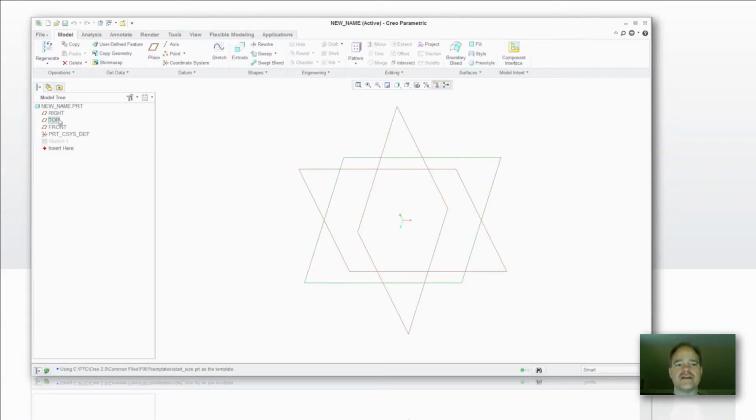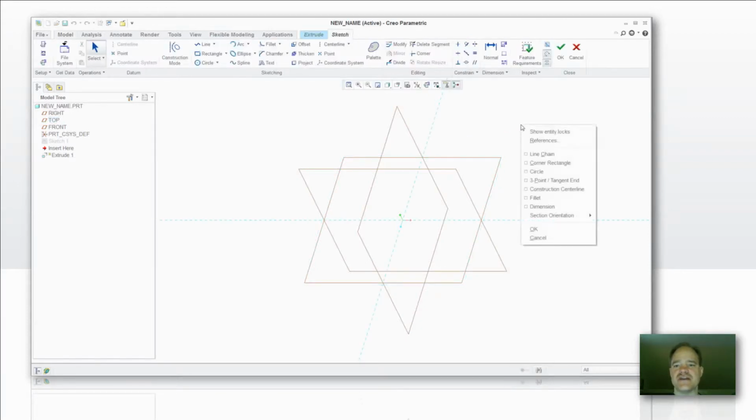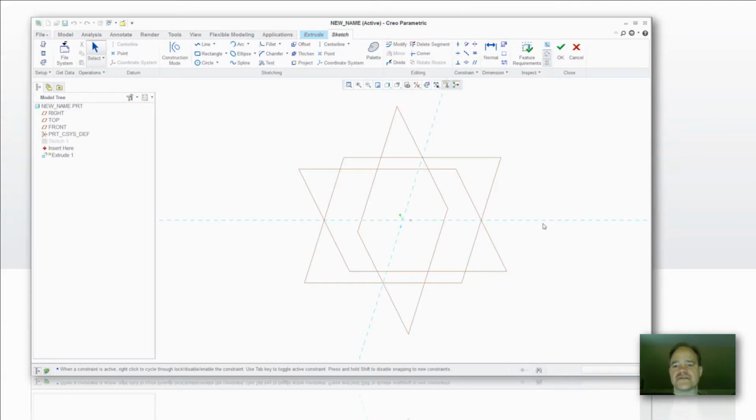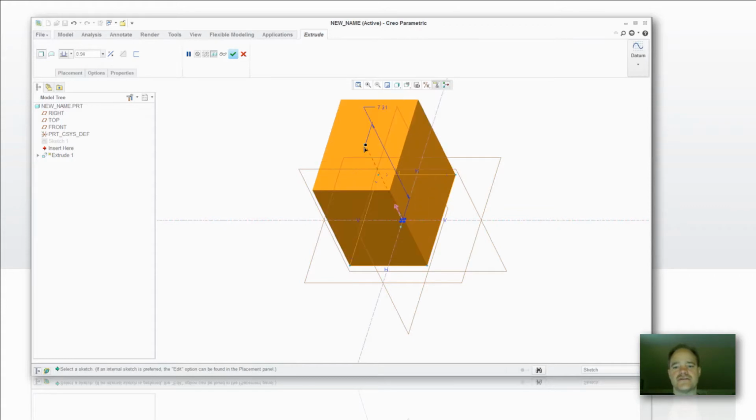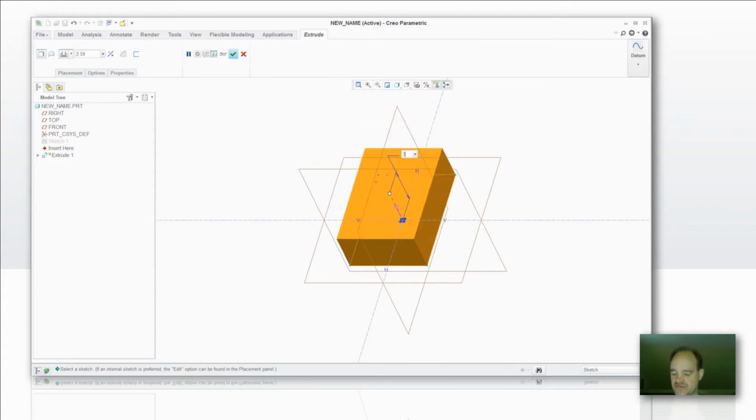Now, when I go in and create my first extrude, again, I've already got that sketch. It's hidden in there. When I come in here and again create my construction center line so that my rectangle will have symmetry. Okay, now I'm back to reality. So in my start part, I set that diameter at a value of 10. So now I have things a little bit closer to the values that I want to have represented. As well as when I go in for my extrusion, you'll notice that the height or the width of the extrusion is back to reality also.